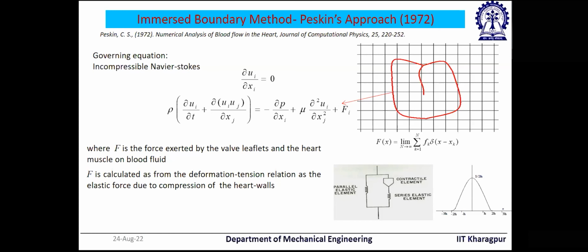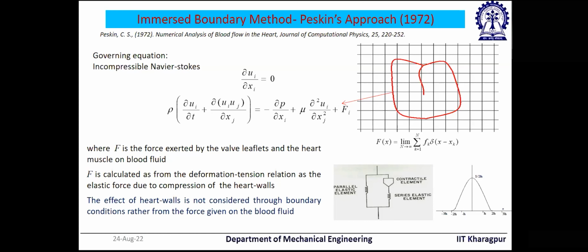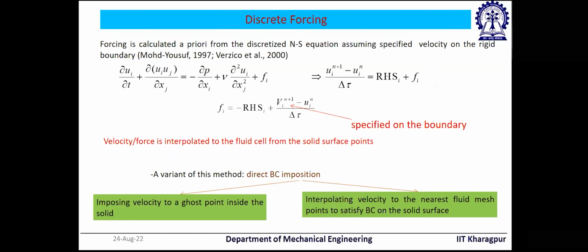For example, if one is using an unstructured mesh, there are algorithmic complexities. Also, there are certain models which are well posed for a Cartesian mesh framework, and there are difficulties in posing those models for complex geometry and complex grids, calculating the right Jacobians, etc. So those difficulties are avoided. Instead of directly modeling the heart wall, their effects are calculated on the Cartesian mesh points.